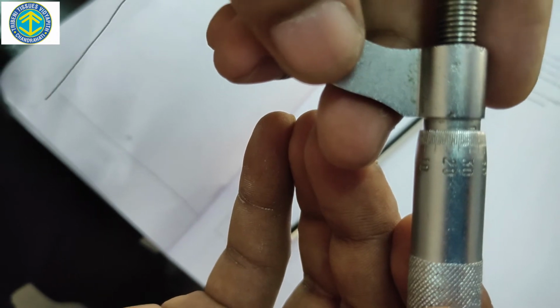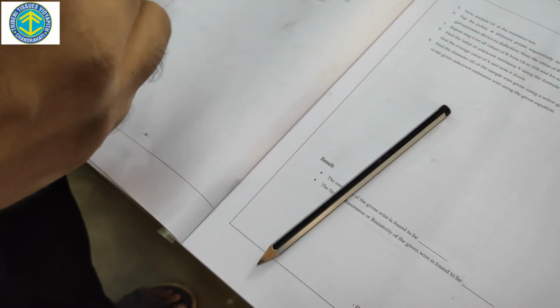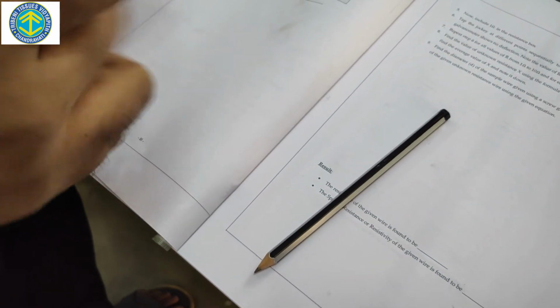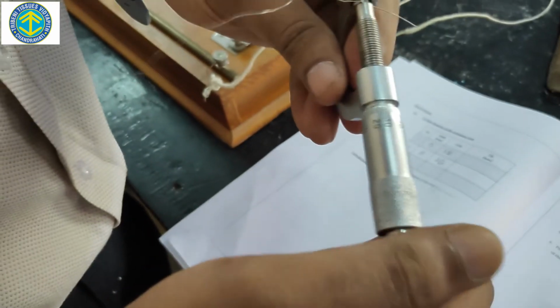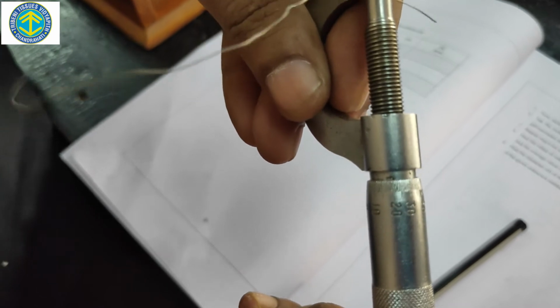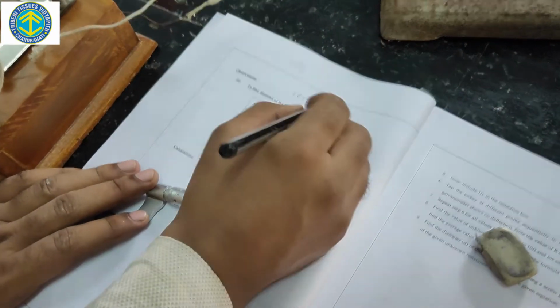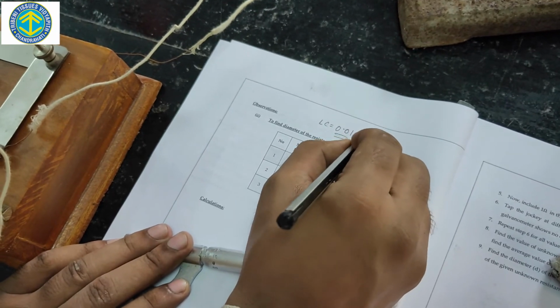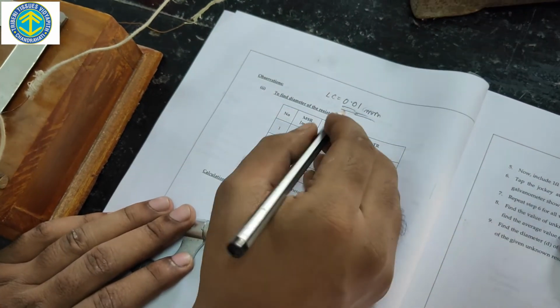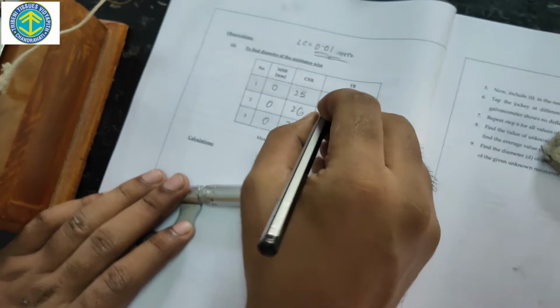Now we'll do it again. And here you can see the main scale reading is 0, and the circular scale reading is 24. So we'll write 24. The least count of this screw gauge is 0.01 mm. So we multiply this least count with the circular scale reading, and we get the true readings in mm to be